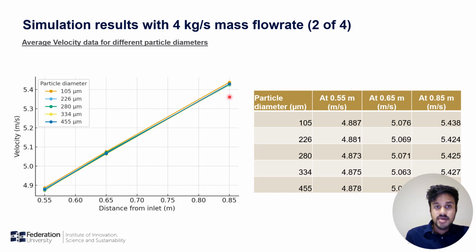The actual reason behind this is that since the smaller particles stay within the core of the curtain, they can reach higher velocities. The larger particles move towards the outer area of the curtain, and these particles have to undergo drag from the air. This makes larger particles slow down.